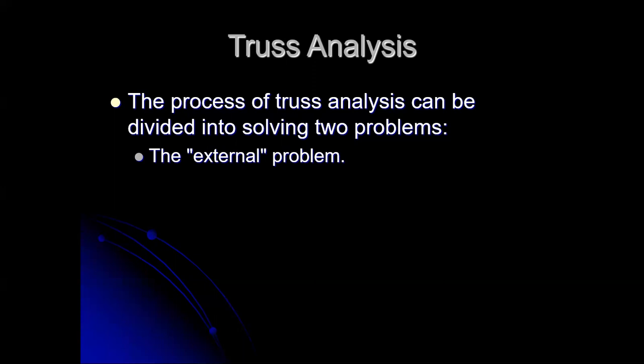Now, that may sound a little bit familiar. It's basically the same problem you've been solving with beams on supports. It's the non-concurrent force system. So the external problem is often our first step. Very rarely can we get away without solving the external problem, but life's usually a lot easier if we solve the external problem first. And we've absolutely got to get that external problem right. If we mess it up, then all of our answers downstream are going to be wrong. So we really have to make sure we get that external problem right.